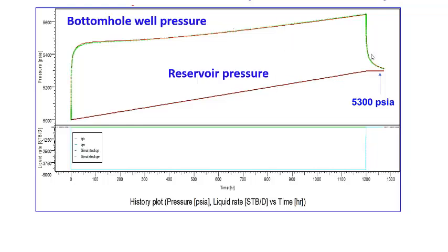And finally, over here at this point, you decided to stop injection to make a fall-off, and then your reservoir pressure is this value here. So you're supposed to get from the fall-off analysis this reservoir pressure here. Later on, I'll explain practical issues regarding how to interpret fall-off tests.